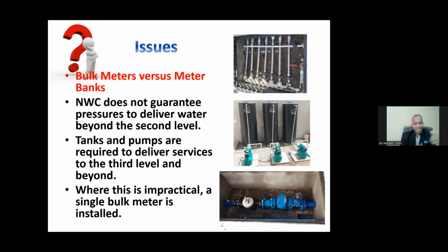Where this is impractical, a single bulk meter is installed. 1 meter, as seen in the picture, is installed. Now, I suggest to many persons when they're installing these meter banks that you have to be very prudent. You can't just install them and not think of how you're going to operate the system, how you're going to maintain the system. In fact, it was just yesterday, I was looking at a particular installation, and the way they have installed those banks of pipes inside that little room, I say, how does somebody walk through the room, much less maintain a particular pipe if it were to burst? How do you walk over that maze of pipes so that you're able to repair that particular one?